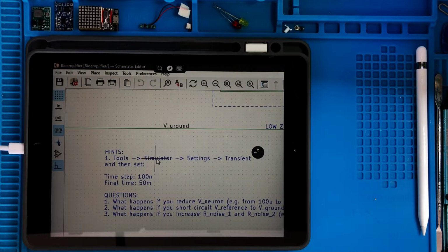The computer cannot solve the circuits analytically. It makes a simplification. For instance, instead of dealing with a continuous variable, it discretizes it in chunks of time and also voltages and whatever. So the simulation proceeds step by step in order to transform everything into algebraic equations that the computer can manage.